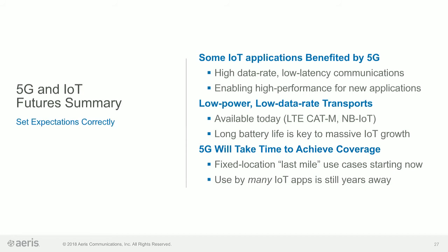So we occasionally get people asking us, if I'm developing a 4G application today, is that in trouble? I mean, is it going to stay in use for a number of years, given the fact that you've seen 2G sunsets and potentially 3G sunsets happening in the next 5 years or so? The answer is yes. 4G is going to continue through 2030, and certainly the low power wide area network aspects of LTE, the Cat-M and the NB-IoT technologies will continue beyond that because they don't take a lot of spectrum. They're in the sub 1 gigahertz and sub 3 gigahertz frequency spectrums available today. And that should allow them to continue being in use because the high performance 5G stuff will probably always be at higher frequencies, 3.6 gig and higher, for the throughputs that they need.